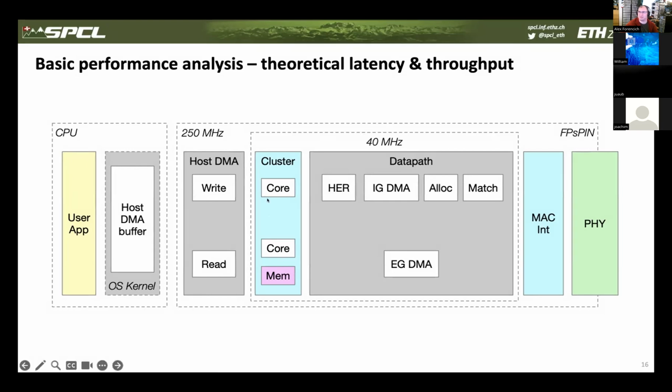Yeah, with this stuff, since there's so much interconnection and integration, it's kind of hard to run one module at a different frequency than another module, right? You've got to figure out basically where that CDC is going to go. CDCing the data path is relatively easy. Running the matcher at a higher frequency and then CDCing all the control signals is potentially a lot more complicated. Exactly. But on the host DMA side, since I don't really know how to properly CDC the descriptor interface, the segmented interface, I'm CDCing the AXI masters, I mean the AXI full interface.